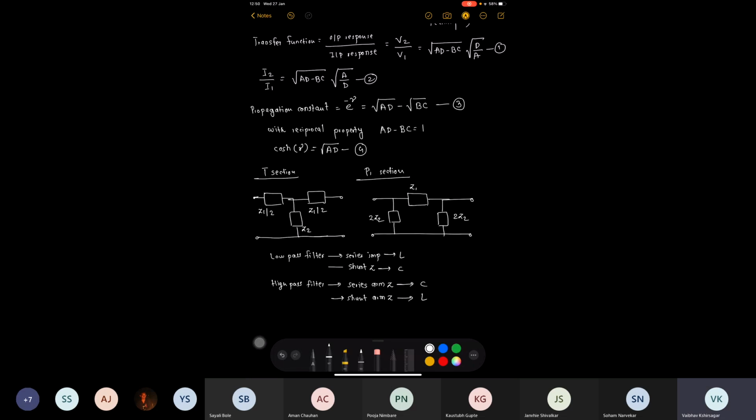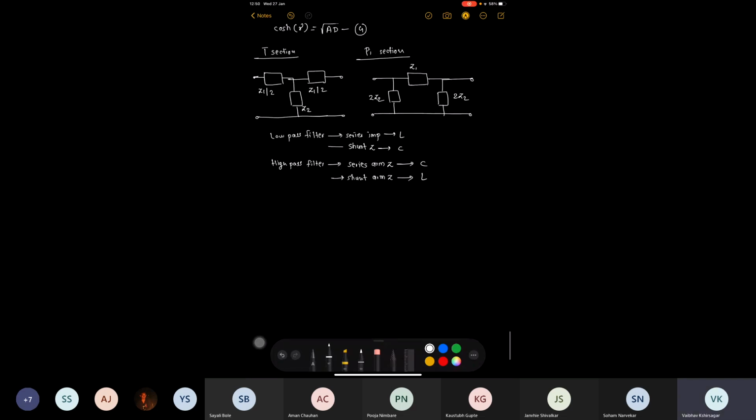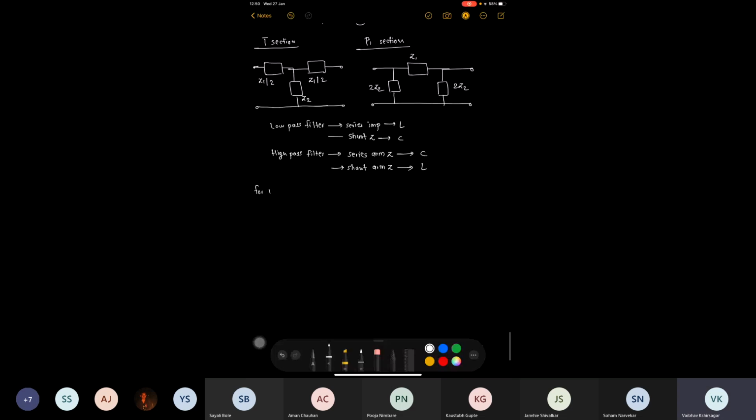so we need to write the low pass T section filter. Okay, so we consider that this particular T configuration we want to design as a low pass. Then the first impedance Z1 is to be given with the inductor j omega L. Okay, and similarly Z2 is the parallel element which is to be given with 1 upon j omega C capacitor.